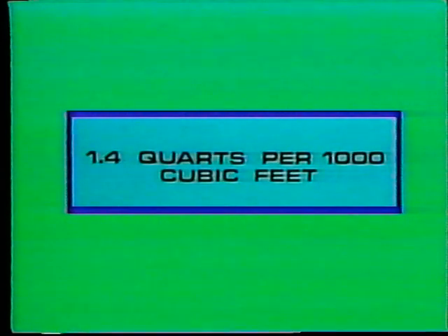Just how important is this? Let's use an example to explain. In many operations, 1,000 cubic feet of air can release as much as 1.4 quarts of water. So even with a medium-sized compressor, say of 100 SCFM, the aftercooler could condense a heck of a lot of water.